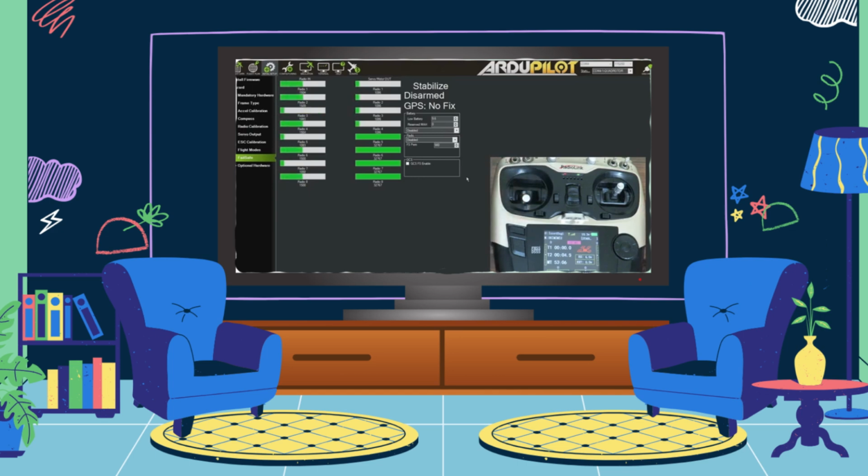Now, to set the throttle failsafe, when we turn off the remote, the receiver needs to detect this disconnection and send a value below 191. So, what is this value? For this, you can see the failsafe PWM value in the radio failsafe section on the screen. This number means that if a value below 980 comes from channel 3, the flight controller will activate the fail-safe mode and switch to the preset mode.